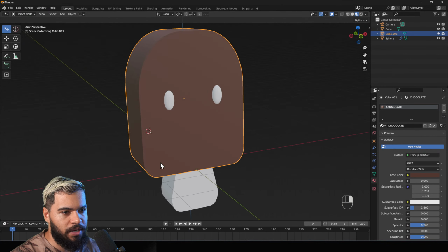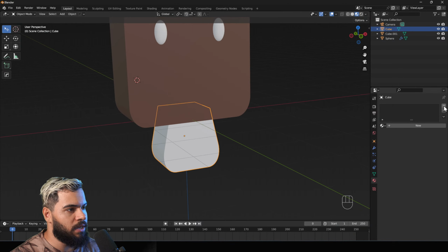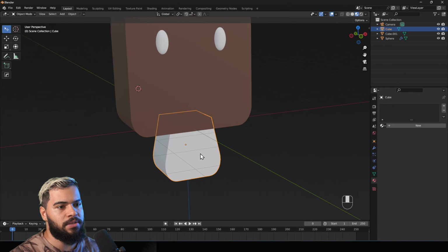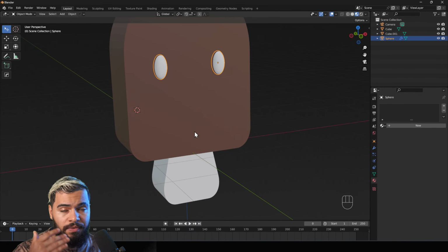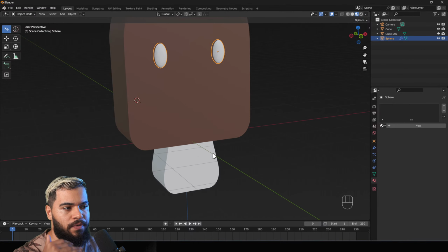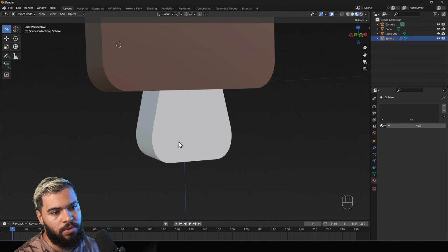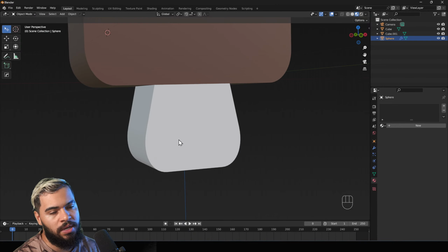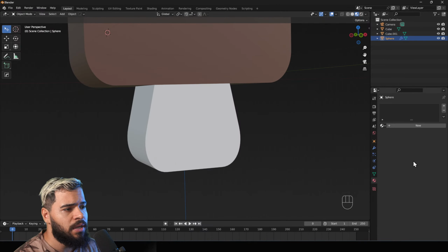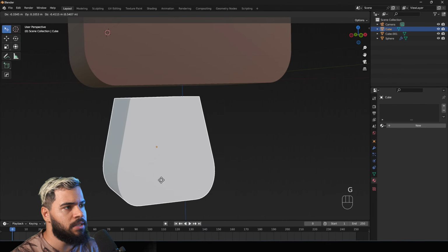And then if I click on the object below, we're gonna have this one. I'll create a material for this one, because as you can see, every single object that you create here in Blender has kind of empty materials, and you need to add materials, which is basically the colors, the texture that you can add later. Okay, I will click here on this object, as you can see, selected.